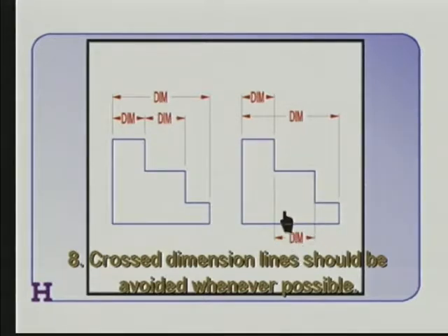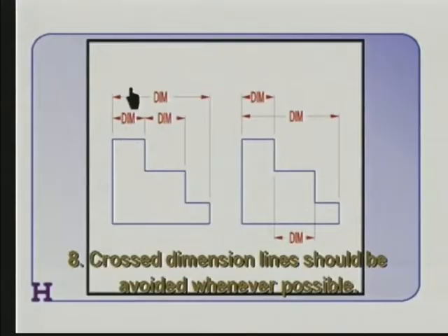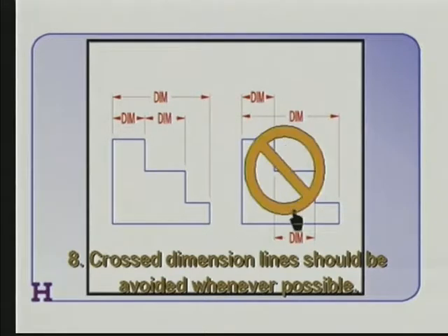Here's a case where the extension lines run across the object and the dimensions placed off the object. But we can avoid this. Now, there are times when you cannot avoid running extension lines across an object, but there are many times when you can. Most of the time you can. The trick, when you're dimensioning, is to go from in to out. Because if you dimension the overall dimension first, you won't have left yourself enough room, and then you'll be tempted to do this double cross trick, which is uncool. We don't like to do that.